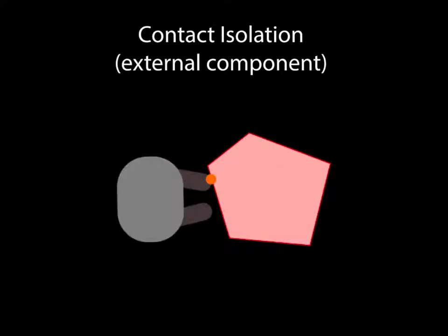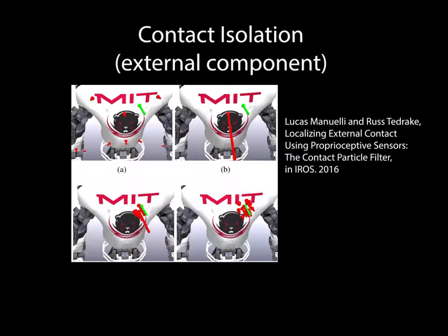Our method is agnostic to how contact points are extracted from each contact. We use the contact particle filter based on estimated external wrenches, but on the real robot, we show how to augment it with more advanced sensing.